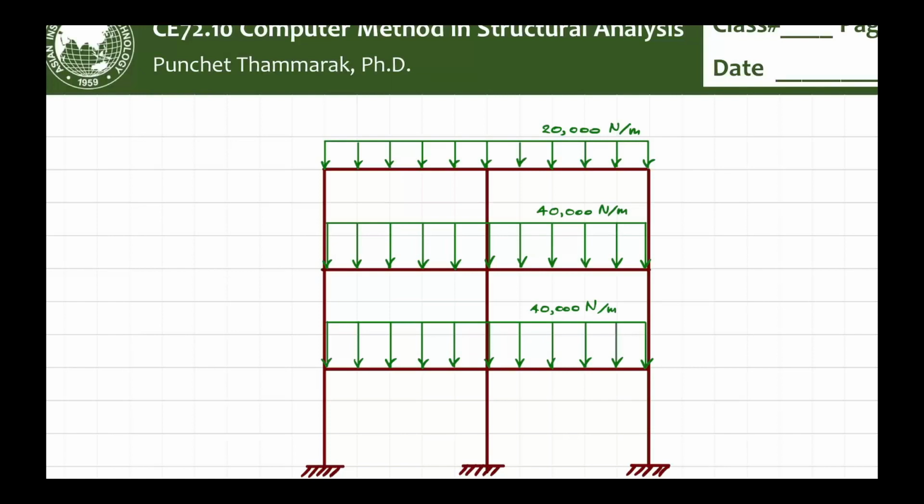It's not a column, so slump might be low, but it doesn't really matter. So lower slump, but less water. Well, you can vibrate and get it packed very nicely as it is a slab, easy to pour anyway, right? And then less permeability will make your slab more impervious to water.